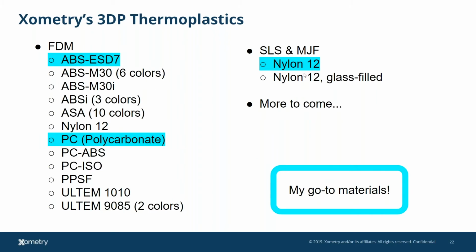And then of course, SLS nylon 12 is that 85%. 85% of the time, this is going to be the right material to choose. As you scale up, look at multi-jet fusion, or say, for example, you do have more snap tabs and more flexible features. Multi-jet fusion may be the material to start with for this.